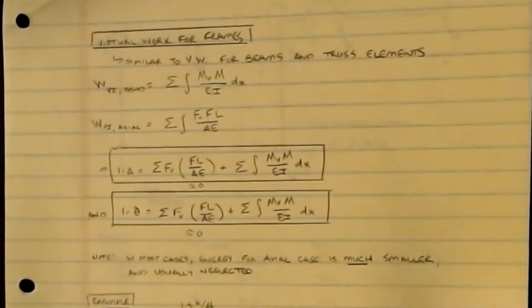Solving deflections for frames can be a little bit intimidating when it comes to hand calculations, but using the principles of virtual work that you've learned in our previous videos, I can show you the basic equations and how simple this technique really is. Before we get into virtual work, we've gone through the derivation of the parts of the equation that are needed for frame analysis in our previous videos. If you haven't already watched the virtual work for trusses video, that's where the axial load equations come from, or the virtual work for beams video, that's where the flexural equations come from. You might want to do that before we move on any further, but the techniques herein are very similar to what we talk about in those two methods.